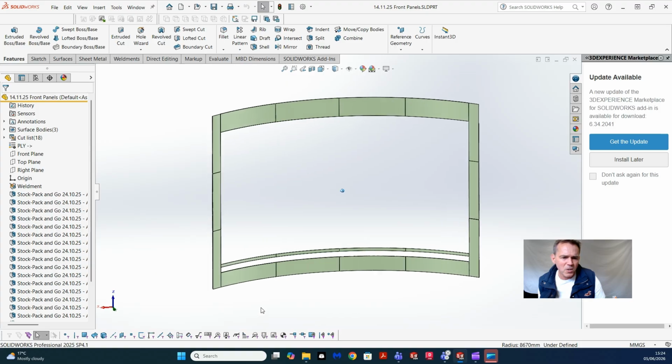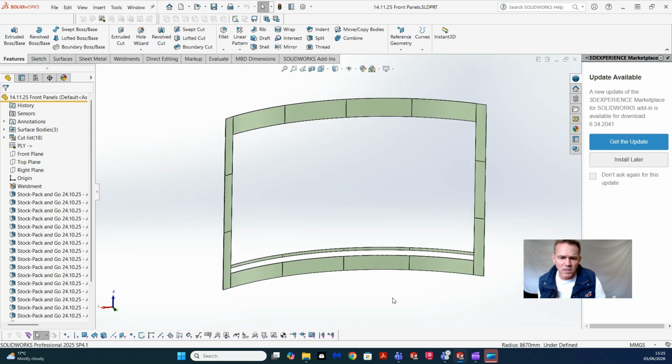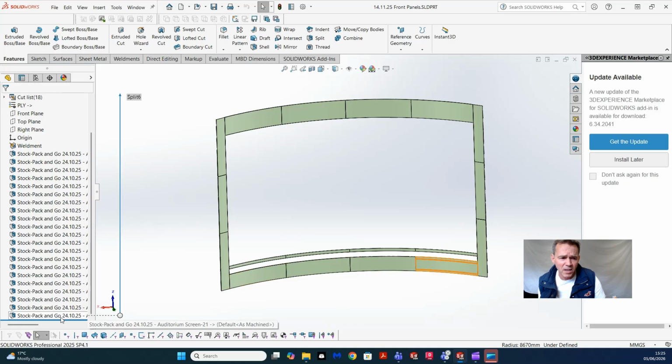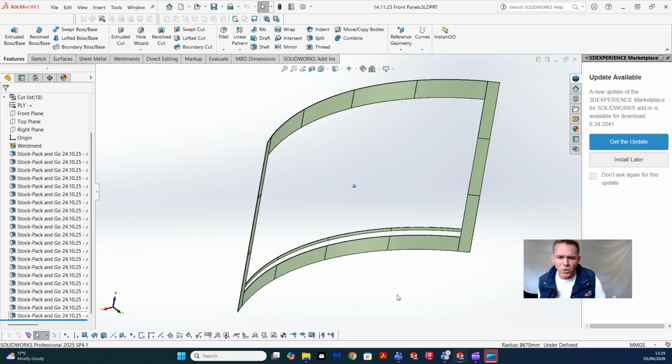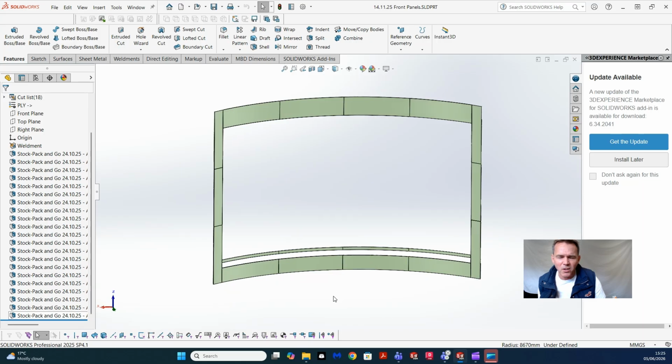It means that all the work to create the geometry for each of these bodies is actually in the previous model, and it's just brought through as a stock part. So it's much more lightweight to work with, and I can now make further changes here, do cut extrudes and whatever, and add on to the bottom of the tree, and you'll find that it's not encumbered by all the processing issues. So you can make those future changes.